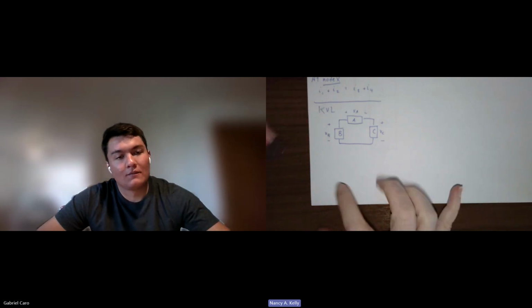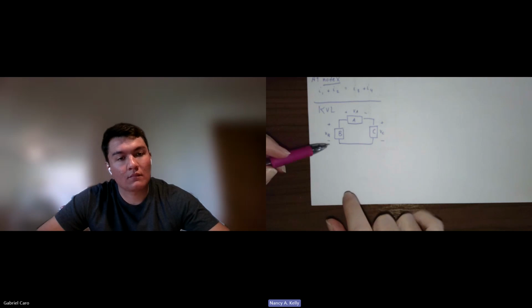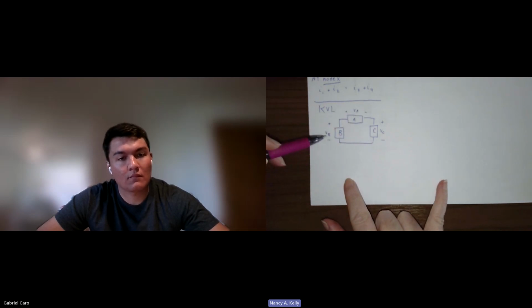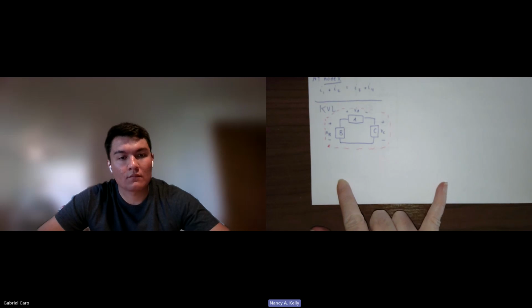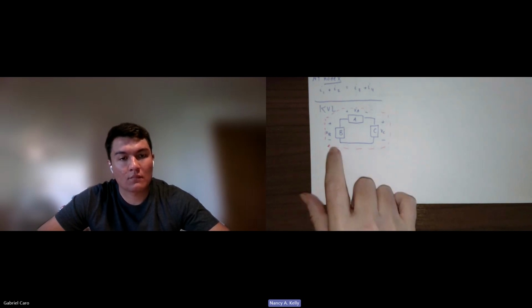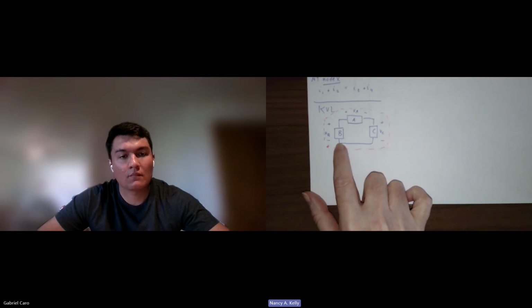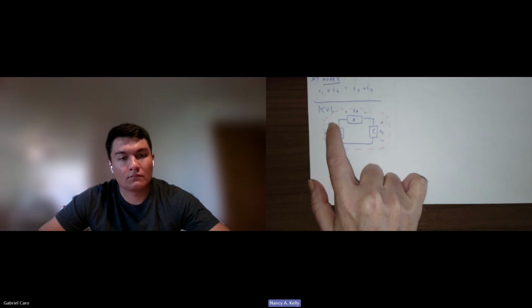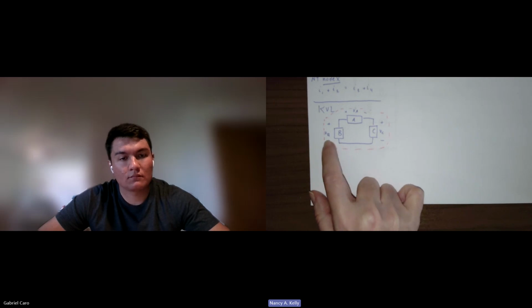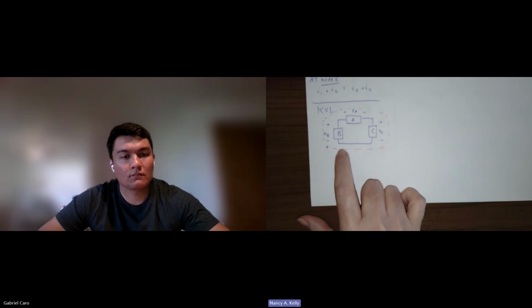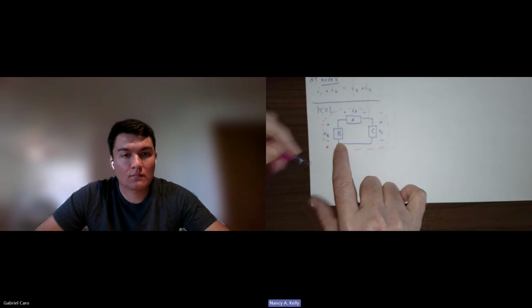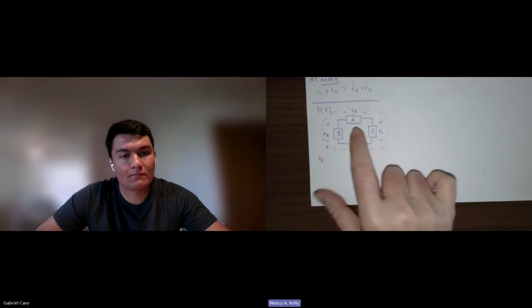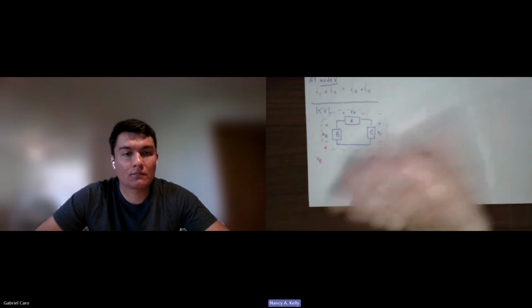These are the basic rules that we use to do circuit analysis. So when I look at this and I can identify a path around which I know all the voltages, I can say I'm going to move clockwise around this path and add them all up. This is the one that is a little bit less intuitive. I just have to pick a place to start. I usually start in the lower left-hand corner, and I see that the negative terminal on this element is marked with the minus sign and the positive terminal is marked with the plus sign. So as I move along this path, there is actually a rise of voltage. Down here is my reference point, and from this reference point I rise by VB volts, so I'm going to call that a positive voltage. Then I come up here. Now the wires we assume are perfect, so you don't see any markings of voltage along those.